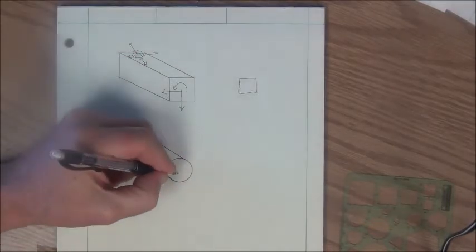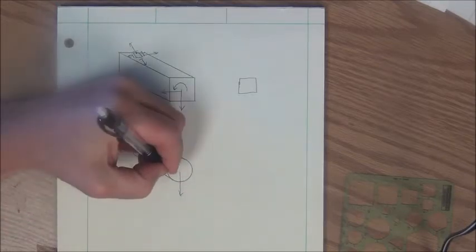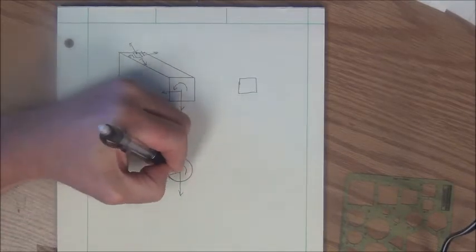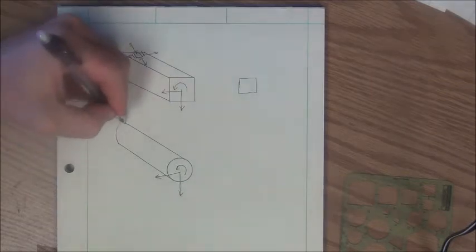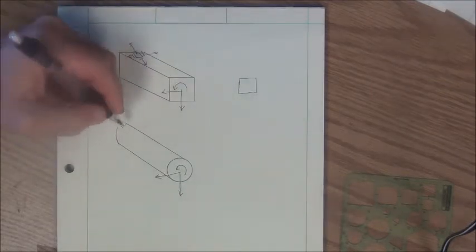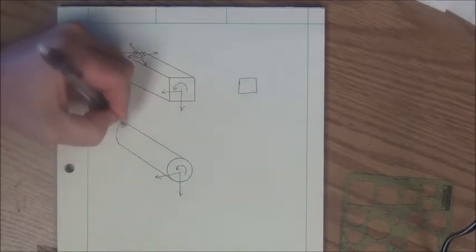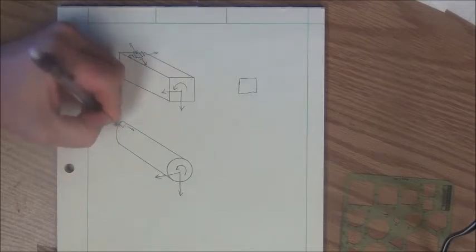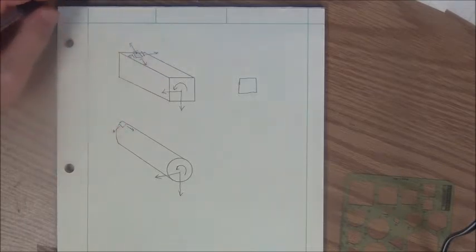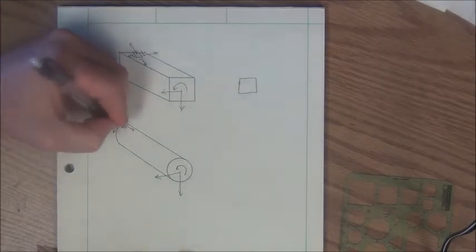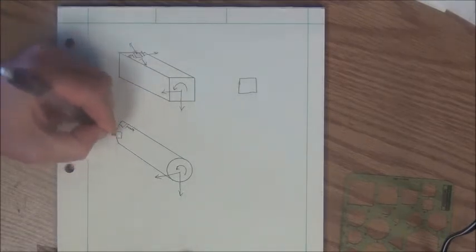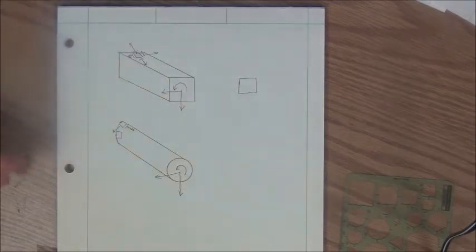The same thing with the circular cross-section. If we put loads on our circular cross-section like this, we could look at stress elements back here on the top of the beam that would have a plane stress state, and we could also look at stresses on an element that occurs here on the side of the beam that would also be in a plane stress type situation.